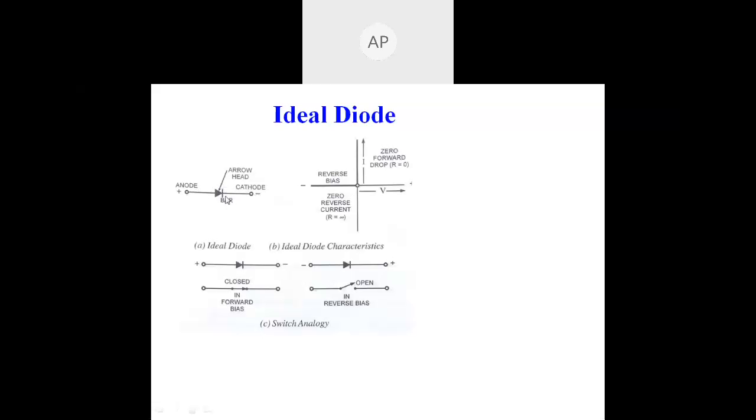This diode symbol can be configured as forward bias and reverse bias. To use the forward bias, the positive terminal of a battery should be connected to the anode, and the negative terminal of the battery should be connected to the cathode. As it is connected in this way, the barrier potential near the junction gets reduced. And for that case, what is the current flowing characteristic?